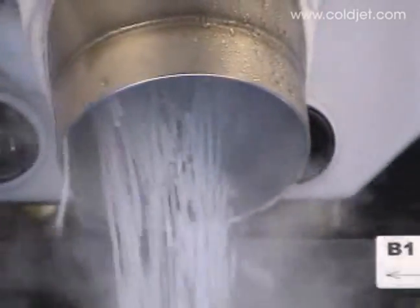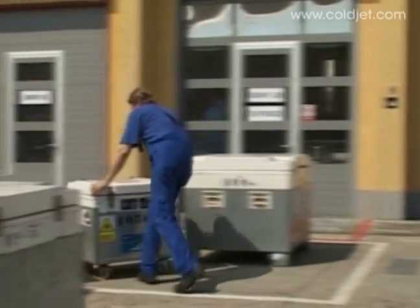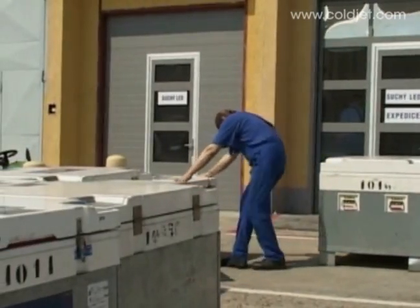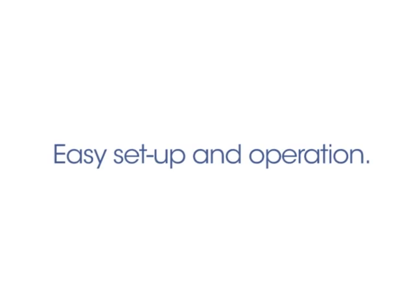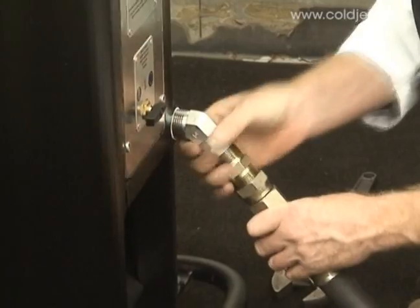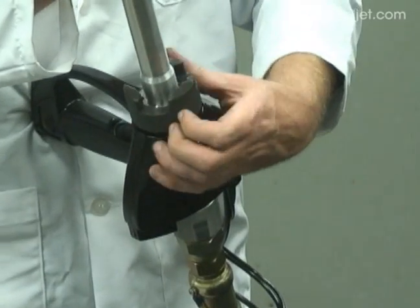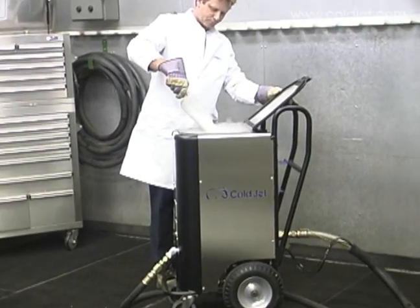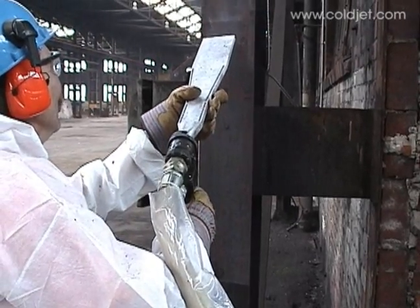And dry ice pellets and blocks are easily available just about everywhere in the world. Just call a producer, schedule a delivery, and you get a nice insulated tote filled with dry ice delivered right to your door. The cold jet machines couldn't be easier to set up. Attach compressed air, plug into standard electric, connect your hose, applicator, nozzle of choice, add some ice, and that's it. Then just start cleaning and saving money.